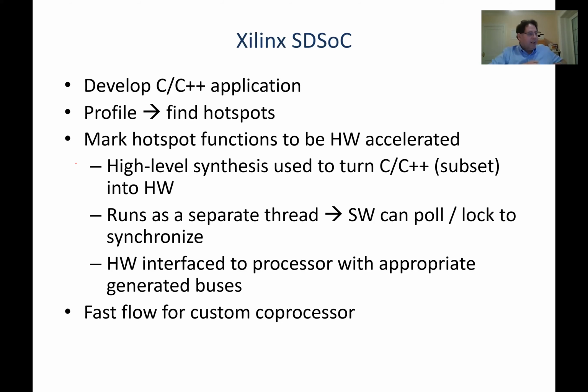And that's all I have to say about programming tools. So there are a bunch of different high-level programming tools. They all stack on top of HDL. In my opinion, it's difficult to do FPGA design without knowing HDL, but you can take significant parts of your system and try to hoist it to the level above, to a tool that will generate the HDL for you. So it's useful to be aware of those tools.